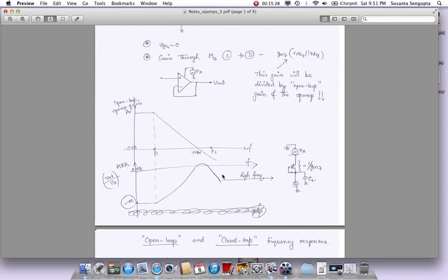That is one thing. What I don't have here, and I should have put it, is that if you keep going down, finally it would even become flat. Why would it become flat? It becomes flat because there is a capacitive value from Vx to Vout. If I refer to this, it will just be the CGS mainly. So there is a CGS value plus maybe other parasitics between Vx and Vout. Then we have this big CL from Vout to ground. So this becomes a capacitor divider circuit.